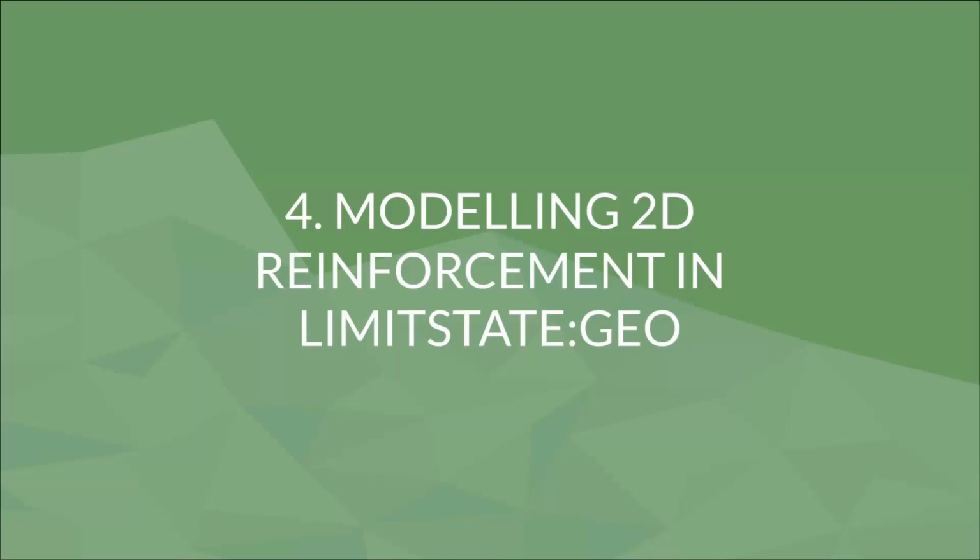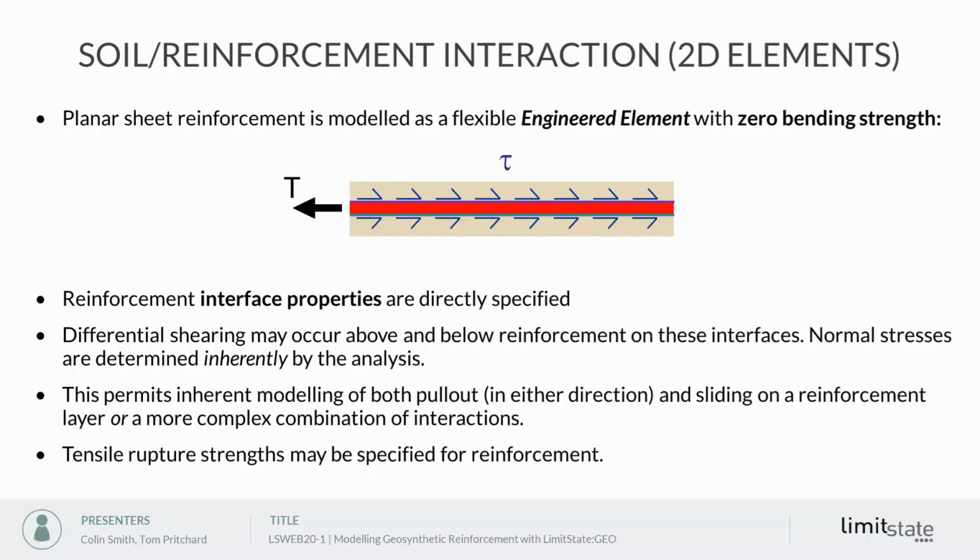So that's the background. We're now going to look at how we model the actual reinforcement in LimitState GEO in 2 dimensions. The software has a specific element within it called an engineered element, and that can be configured to model 1-dimensional or 2-dimensional reinforcement.